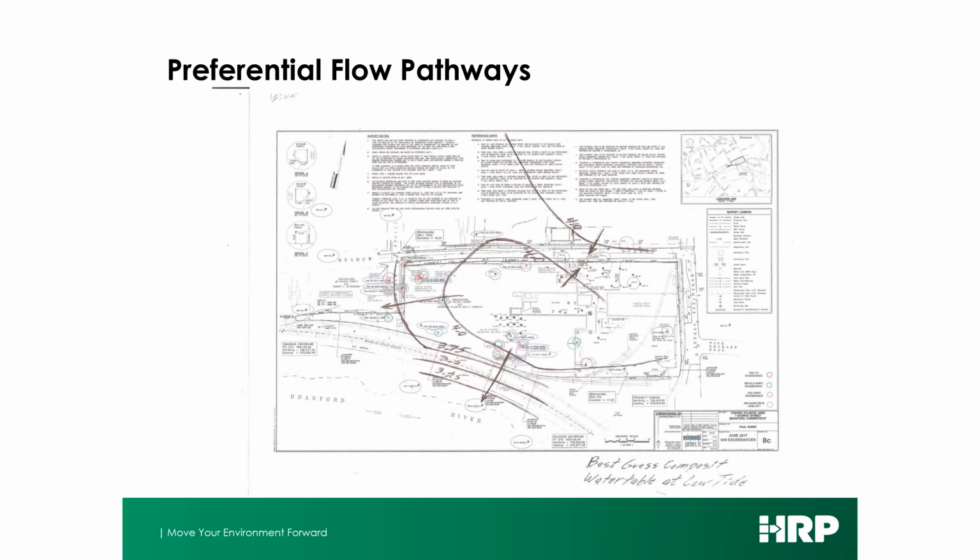What's really happening out there, in my opinion? So, the railroad track was built across the wetland, which means they excavated out most of the material that was there, filled it all in with low permeability stuff, compacted it. The railroad track's probably been there for 150, 200 years. Low permeability zone.